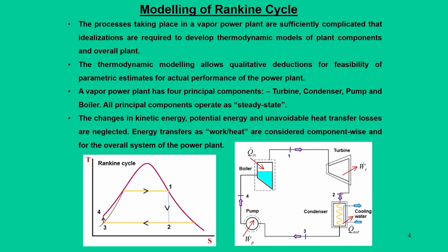In addition to that, we also have to see that the heat addition process in the Rankine cycle is increased, because in the heat addition process there is 4, 5 and 1. In this heat addition process, at constant pressure, that is in a TS diagram under constant boiler pressure, the system goes from 4 to 5, and from 4 to 5 we are essentially adding heat to bring the state of the liquid to the state of saturated vapor at point 5.